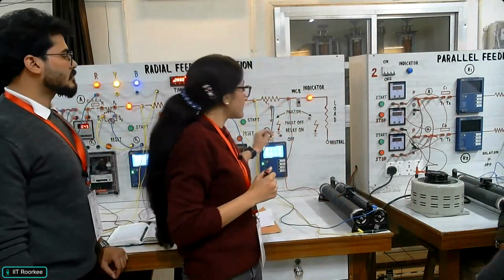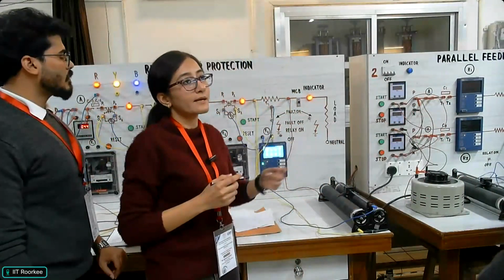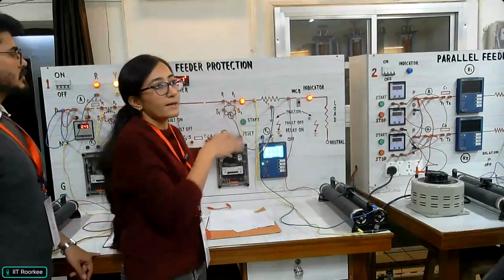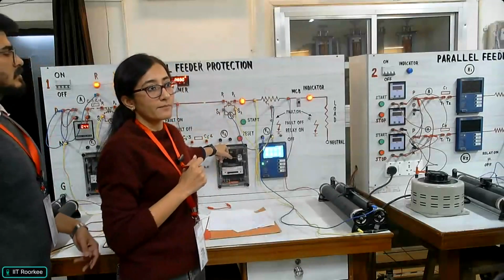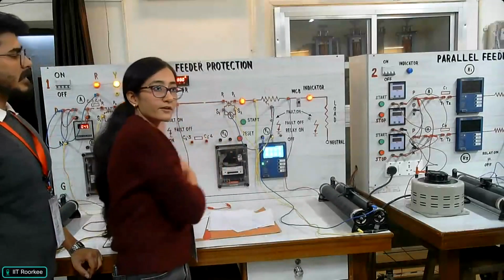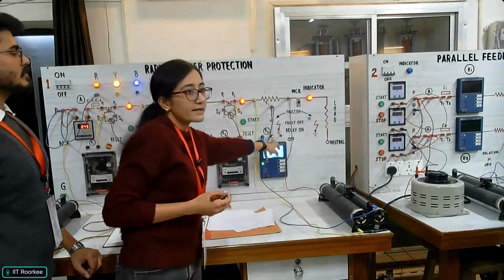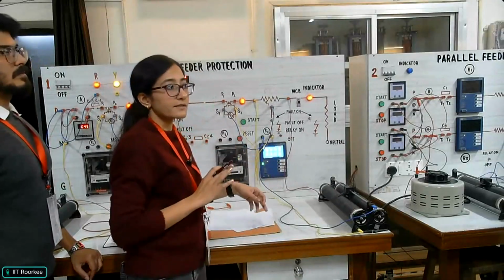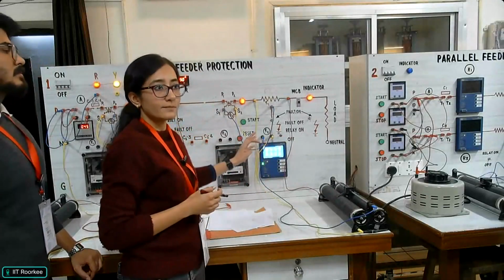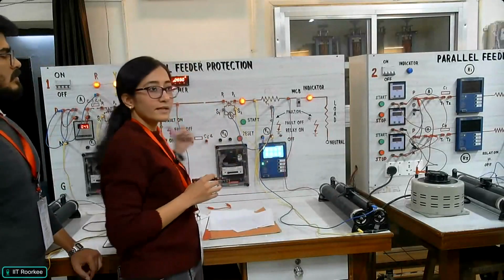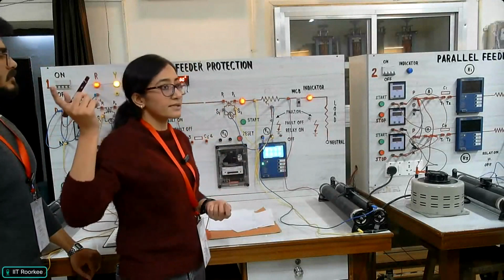Secondly, these relays, for example, follow IDMT characteristics. If for our application we need inverse minimum time characteristics or very inverse characteristics, then we have to use a different relay altogether. But in these newer generation relays, we can directly feed in our characteristics. We can even write our own custom characteristics. Secondly, these are communication capable, so within-relay communication, as we discussed in our lectures.